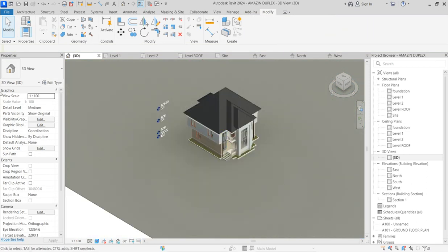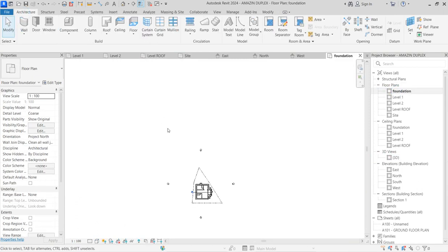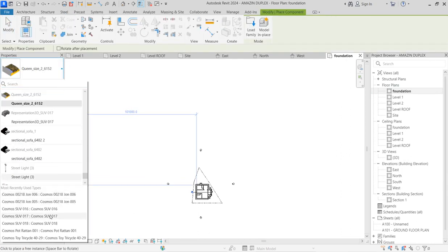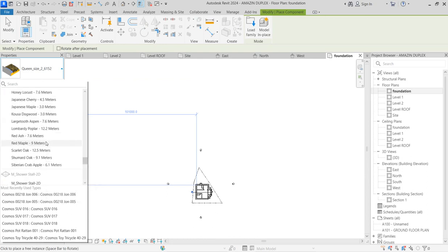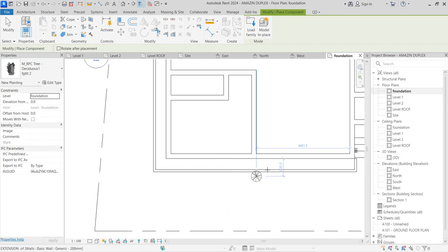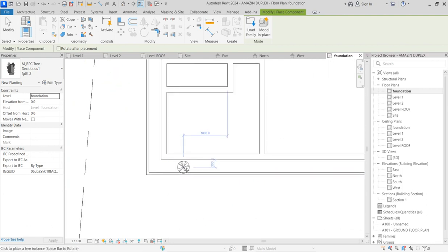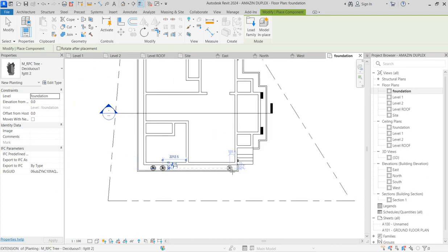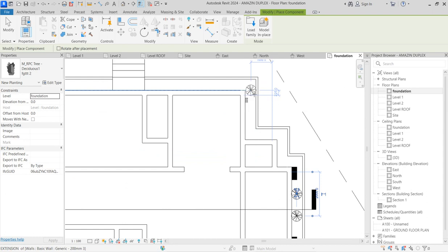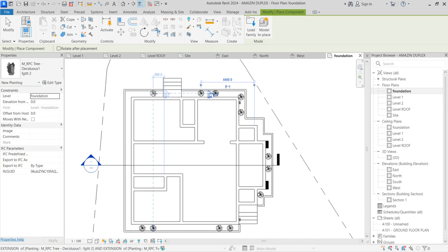So the next thing we need to do is to bring all these flower pots into this place. So go back to the foundation. At the foundation, select architecture, and from the architecture you click on components. Here you select all the components of the flower, whatever is okay for your own use. I'm selecting this because some of these have already been used in these particular references. So I'm taking this up. Good. So make it in this place. Set it up here. So bring 2. Okay, and set it here. All this is going to reflect in your elevation.